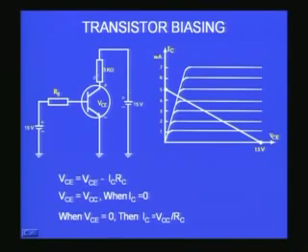And obviously, you can see this can be done in more than one way. Now, you can see on the left side there is a circuit which is again in common emitter configuration, and you have connected your RB, the base resistance, along with a base voltage source VBB. Similarly, there is one collector resistance, which is here 3 kilo ohm, and that is connected to another collector emitter voltage, which is 15 volts, the VCC supply as it is called. Now, can I use this circuit to bias the transistor?